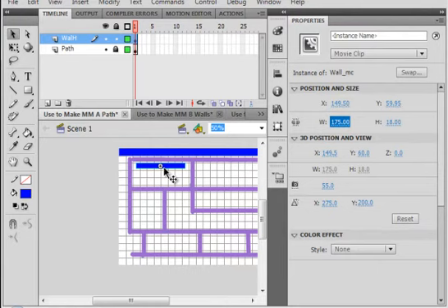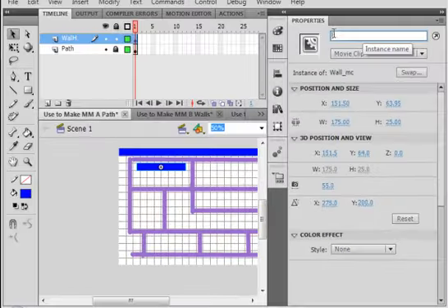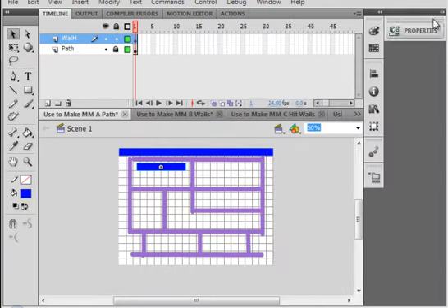And this height, we want to make sure that stays 25. And let's put that right there using my arrow keys so that it's in between these two grid lines and halfway in these two blocks. This one's going to be wall WH2 underscore MC. I'll do a few of these with you, then the rest you can do yourself.